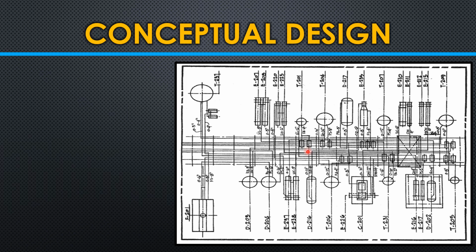Even line routing will really help you to rearrange the equipment to finalize the equipment layout. So that is why, even in equipment layout development, we have to do the preliminary line routing in order to understand and ensure the location of the equipment is right.